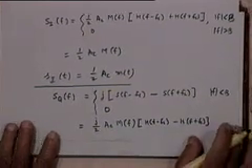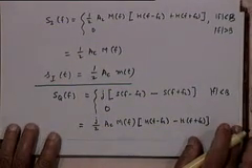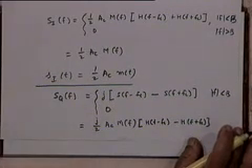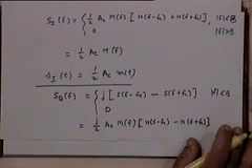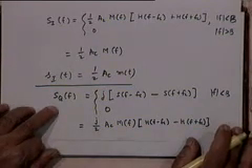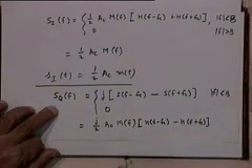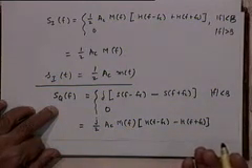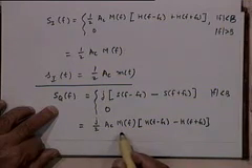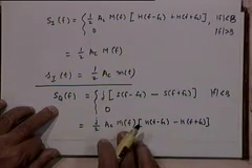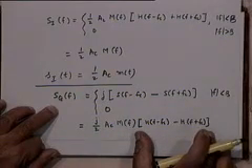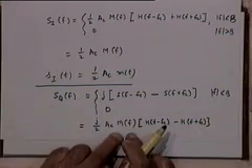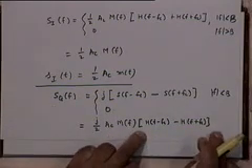Okay, that's what you will get. Now how do you interpret this result? The interpretation of this result is that the low pass signal S sub QT, which forms the quadrature phase component of the VSB signal, can be obtained from the message signal MT by passing MT through a filter whose transfer function is this. You are multiplying the spectrum of MT with this transfer function.